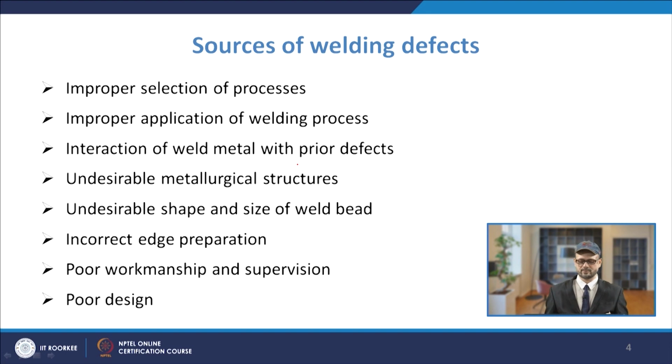We have studied lamellar tearing, and the interaction of laminations with these impurities may result in that kind of tearing. So, that is because of the interaction of the weld metal with prior defects.